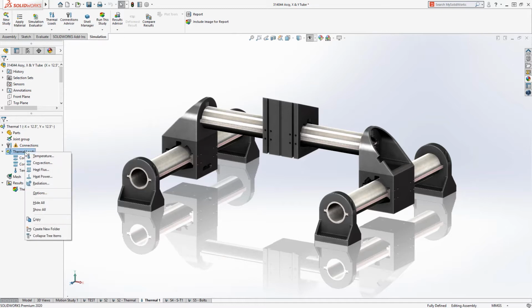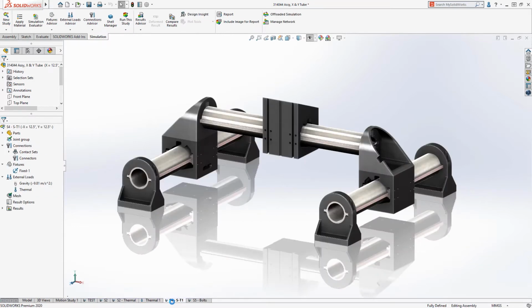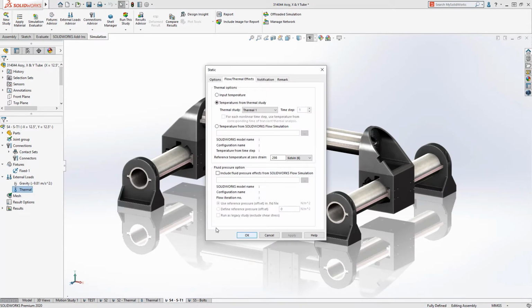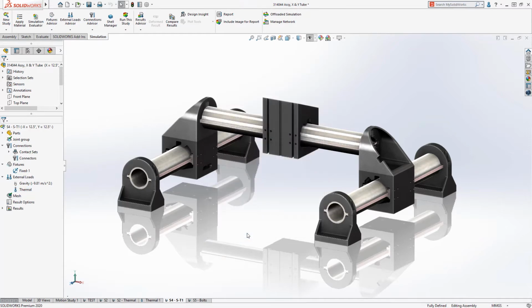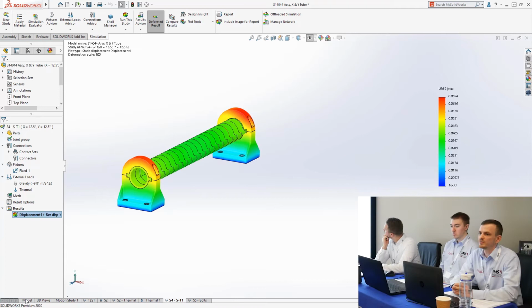Moving over to the full-blown thermal analysis, you can see we also have the options for our heat power, radiation, convection, and so on. So we can then start to view our results on all of those beam elements that we have set up. Last but not least, we can pull those thermal results into a static analysis to look at those deflections. For example, on this OMAX waterjet cutter, we need to have some pretty precise deflections. We need to know what those are, so we can now simulate them using our beam elements, speeding up your process.